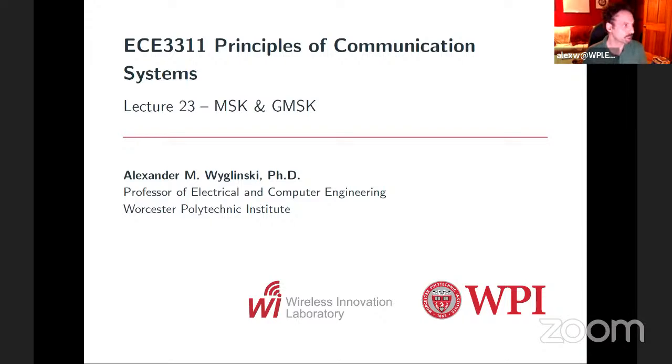So we saw this before with respect to things like discontinuous FSK, where if we try to communicate information, we had these abrupt changes between this is a 1, this is a 0, right? Now, binary 1 and binary 0 representation, which is two different frequencies. And this creates a lot of messiness, because it has this awful discontinuity between the two symbols.